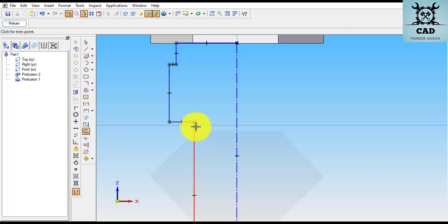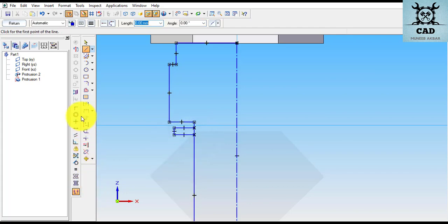there is a gasket at this position at the same level here. So we have to draw that at a small distance. So let's draw this line, and next of 1 mm, and this line. Now I'm going to use this command.